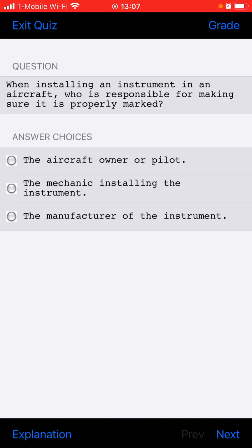What safety precaution must be taken when removing a wheel from the axle or when disassembling a wheel? Verify that the tire is completely deflated before removing the wheel from the axle or before the wheel disassembly. Why are fusible plugs installed on some aircraft wheels? To release the pressure generated by heat buildup before the tire blows.